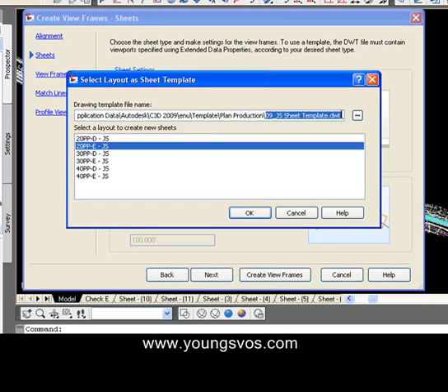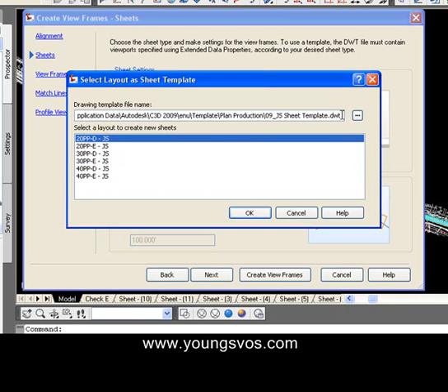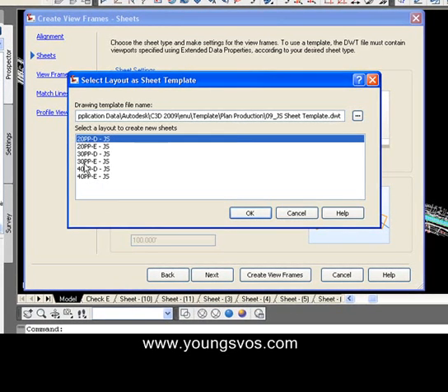Okay, this one in particular was created by a gentleman named Tench Tillman, the owner / operator, whatever, janitor, I'm sure he does everything there, of cadpilot.com. So the fact is, when you set up that sheet or you use his, it will bring in for you any kind of views in this list down here of what's in that particular template. So you can create your own template, meaning you can put your own title block in that template, and you can create any number of the sheets down here at the bottom tabs in here for 20 scale, 30 scale, 40 scale on a D or E, or I mean, you can do whatever you want in that drawing.